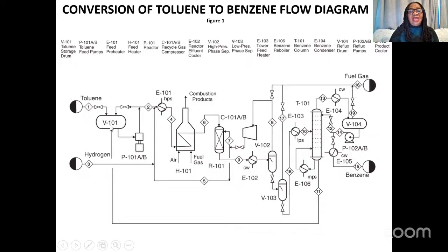That's why we're told that it's almost horizontally just below what is written about it. So like you see V101, you look for it on the left side. If you want to look at V103, you see V103 is written up there, almost in the middle, thereabouts. You just go down there. It's almost horizontally below it. So that's how you identify and locate where your equipment is.